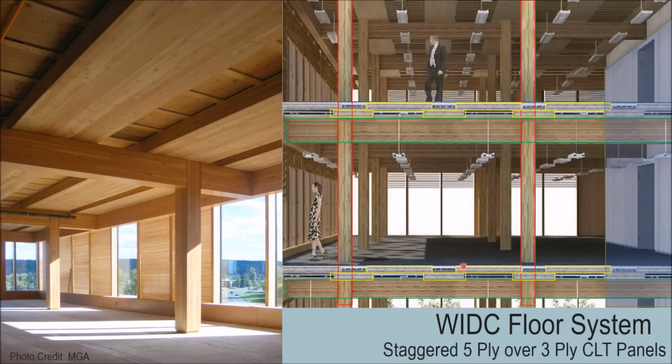This staggered system has a lot of connection at this deeper section to create deeper ribs, if you will, that span in that direction. So just another creative application of CLT in a floor system used in conjunction with the post and beam framework.